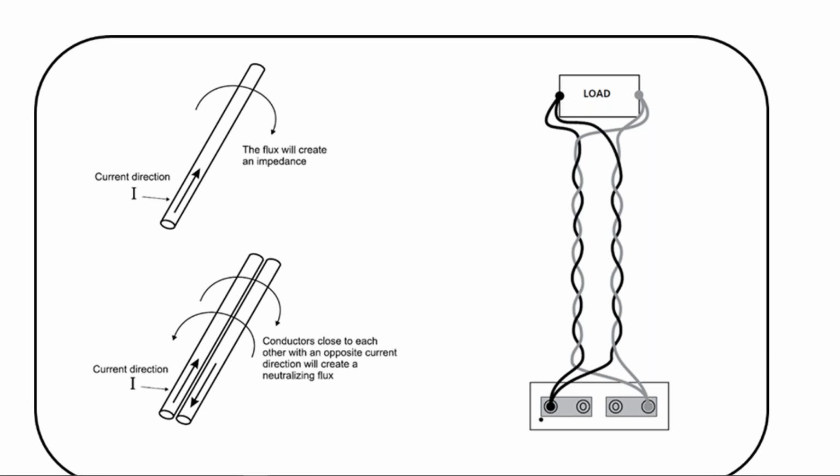When we say, okay, you have to create twisted pairs of those conductors, we mean that you have to take one conductor of each side of your current box to create those twisted pairs. Again, I've met it many times, especially when I have more than two cables per connection. It's really easy to get it wrong and twist two cables from the same side of my current box, which will accomplish nothing in terms of reducing the impedance. And again, really easy in the field because